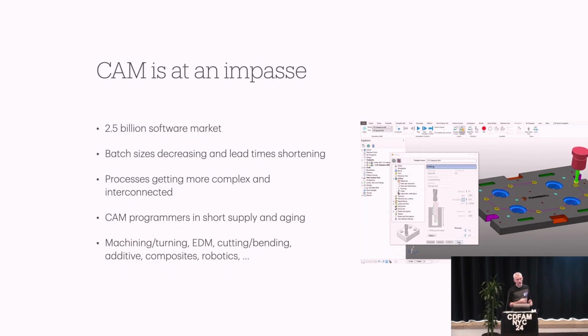Also, manufacturing processes are getting significantly more complex, like a 3-axis milling machine versus a multi-axis 5-axis milling station. It's very, very different. For those that haven't seen real-world CAM software, it has 100 buttons and pages of things you need to be setting up. It typically takes a CAM programmer years and years to build an intuition on what all these settings actually mean when you physically produce the part.